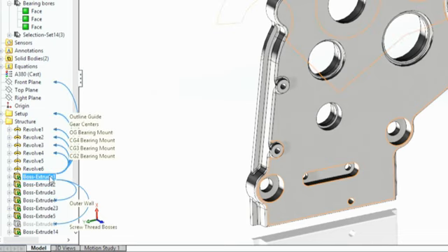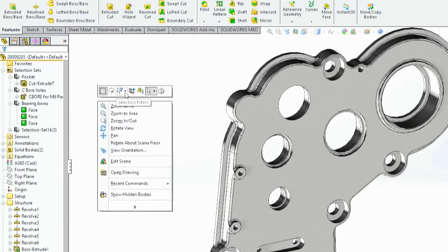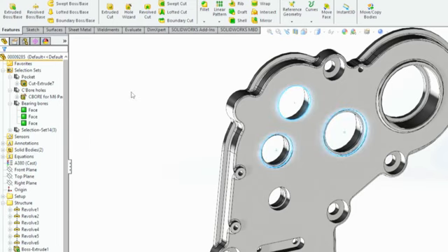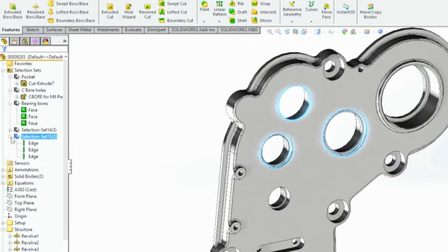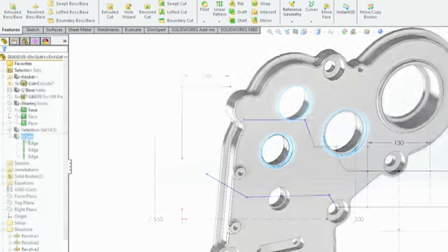Solidworks displays a graphical parent-child relationship between the features, making it easier to determine dependencies in parts and assemblies. A new selection toolbar is available, providing easy access to the most common selection tools, filters, and even previously selected items. For commonly picked items, selection sets can now be saved and include geometry, features, components, or drawing items.